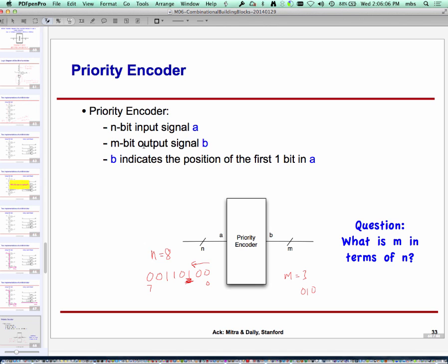So you can express your logic in these terms, and then you'll get your initial equation, and then you can use Logisim to design it. Or I also sent around on Piazza a link to Wolfram Alpha, which I like to use quite a bit because it can do a lot more manipulation of Boolean equations. It asks you to write them slightly differently, but it gives you in one go many different ways of expressing that equation. So I find that useful also. And then you can translate them back into logic.